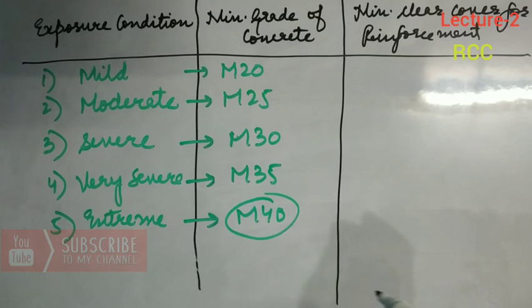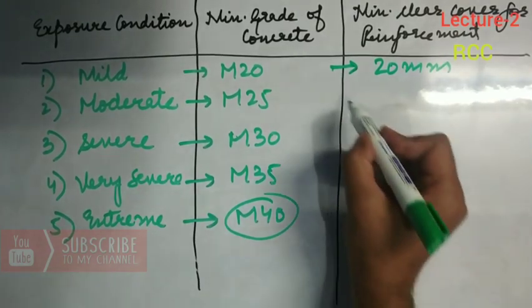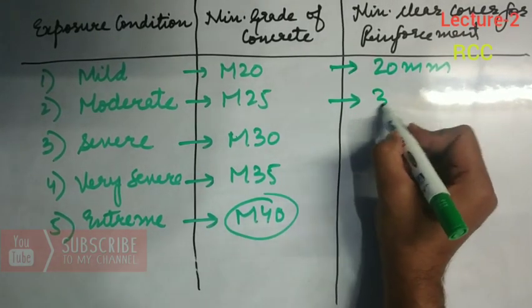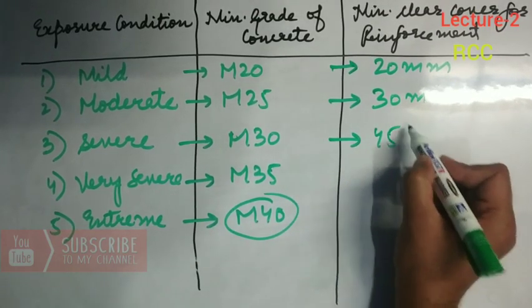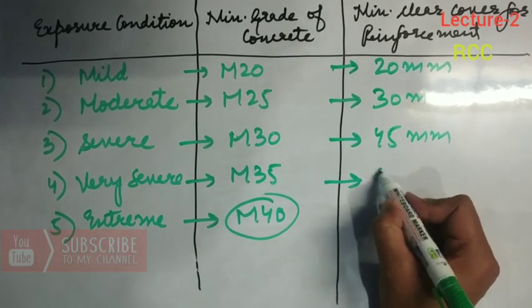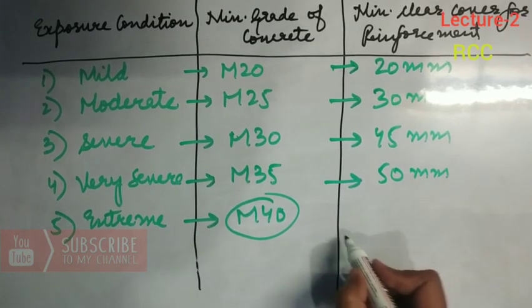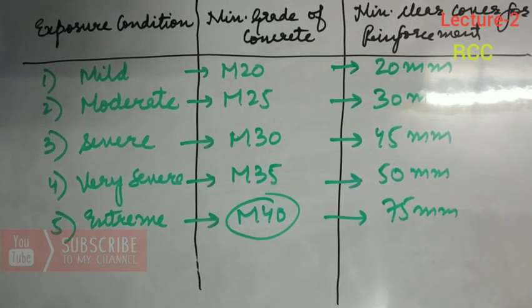Now we also have minimum clear cover for reinforcement as per the exposure conditions. So for mild exposure condition, minimum cover is 20 mm. This should be remembered. For moderate it is 30 mm. For severe condition it is 45 mm. For very severe it is 50 mm. And for extreme condition it is 75 mm. So these were the exposure conditions and the minimum grades and minimum clear covers for reinforcement.